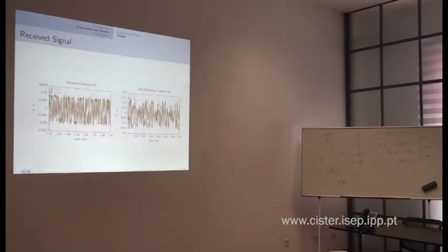And then, as a consequence, when you get the beating, the frequency of this modulation here is actually the frequency difference between the two carriers. So if they are very equal, then they will still have it, but it's very slow. It will be like a bump here, very large, and then it will go down here, right? So you can think of, what if we manage to make them so tight that there is this big, long bump, and then comes the depression.